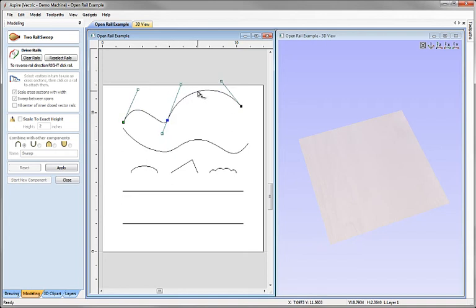And you need to learn the different shortcut keys that are available here, or use the right mouse click menu. You can see I can right mouse click, say I want to insert a point there, so I'm able to make edits to this. I can change the vectors. I can even come down and click on the points and change the cross sections as well. So you can see we've got quite a different selection of shapes here at the moment.